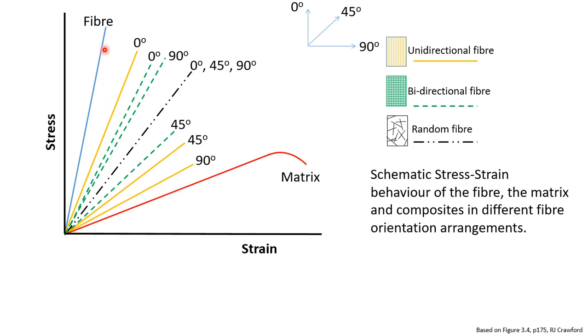Now you can see that when the fiber is going to fracture, that means we are applying the maximum stress in a composite. So fiber will break when the strain is here at this point in this case. Therefore in any composite, failure will happen when the fiber actually fractures, and fibers will fracture at a much lower strain than the matrix because the matrix can sustain much larger strain than fiber. The stress value of the matrix should not be the ultimate tensile strength of the matrix, but rather the stress at the strain at which fibers fracture.